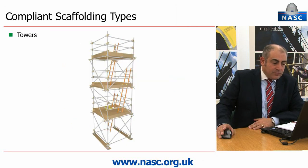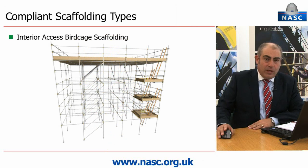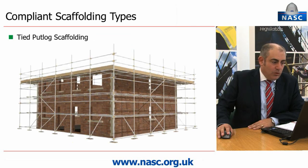Towers, we see changes to the safe height to base ratio calculation for static towers erected externally or with a wind load. We see compliant scaffolds for lift shafts, but mobile scaffolds in tube and fitting are no longer included. We see the welcome introduction of compliant interior access birdcage scaffolds, tied put-log scaffolds,